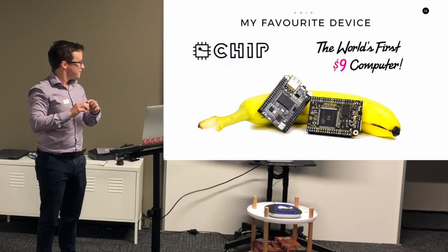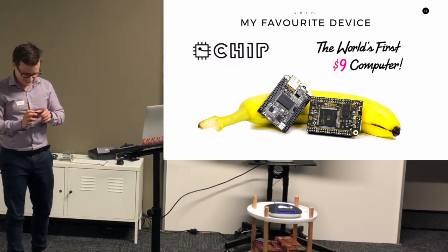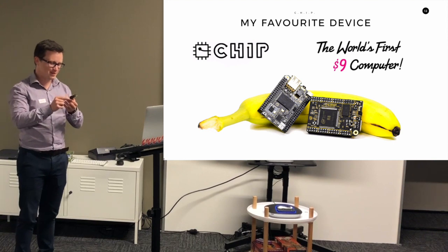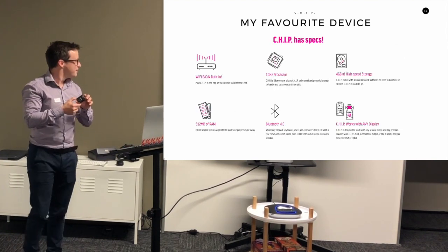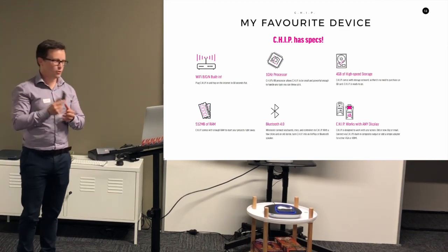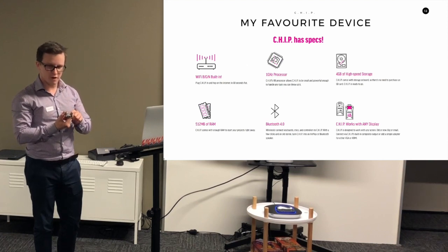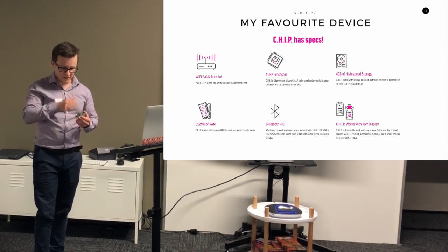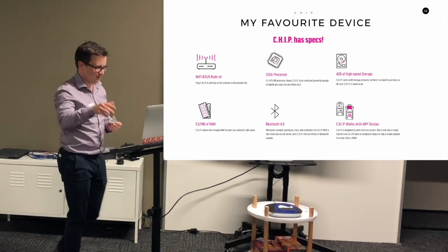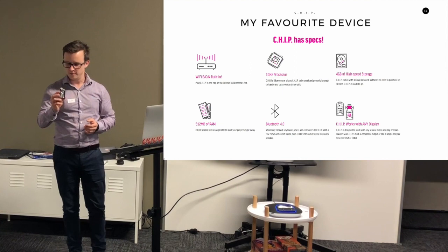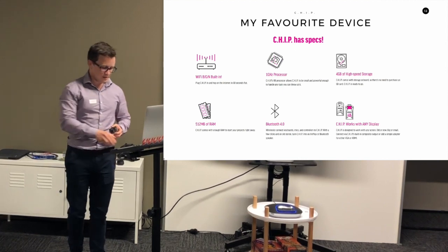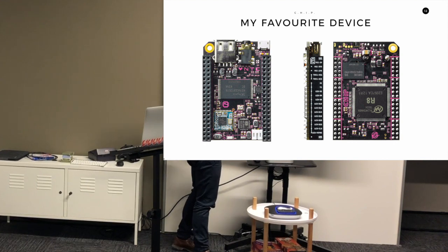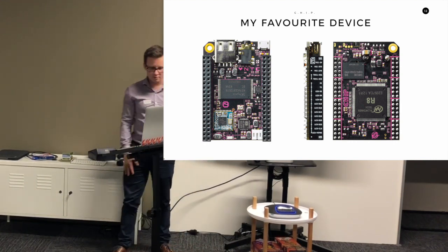So, this is a CHIP. This was $9, and it's actually got some good specs. As soon as these came out, I bought 5 of them. They've got built-in wireless with Bluetooth, and onboard memory, 512 megs of RAM. It will never crash unless you're running 1 gig. You can run headless. I think I'm running Debian or something like that. And much like the Raspberry Pi, it's got these risers with 5 volt, 3 volt, 1 volt outputs, so I can use those as digital switches.